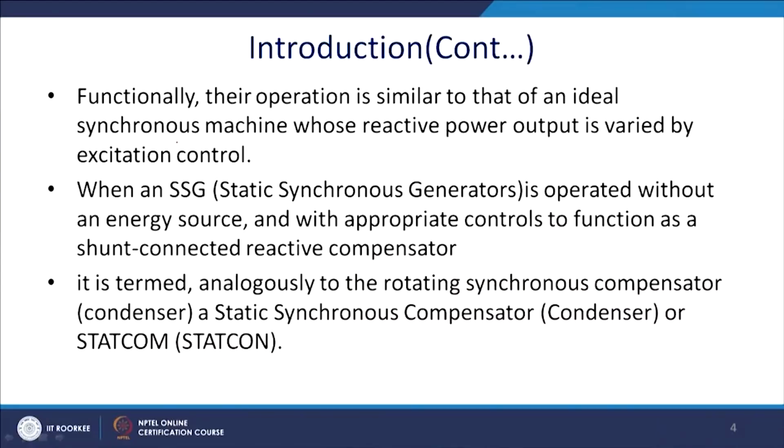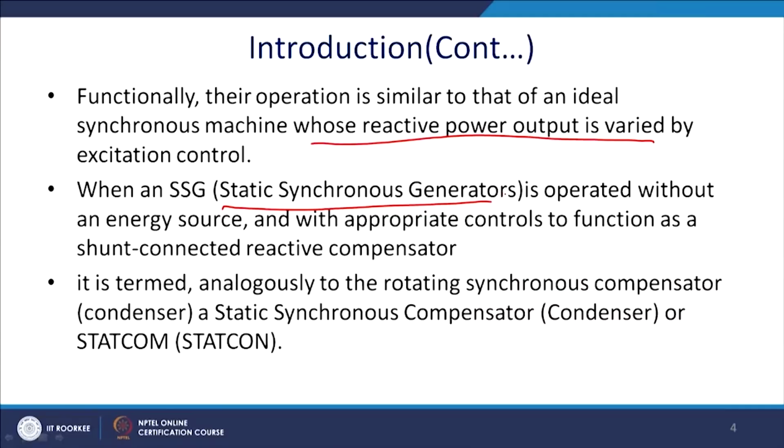and functionally this operation is similar to an ideal synchronous machine, an over excited synchronous generator compensating the VAR, whose reactive power output is varied by changing the field excitation. Essentially you have a static solution, where generally you had the rotational solution. When this static synchronous generator is operated without energy sources, with appropriate control, it functions as a shunt connected active compensator, but the other is a rotational solution.